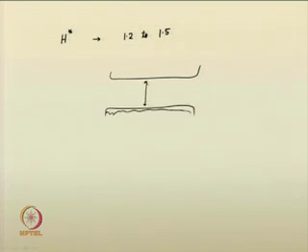This is the culvert depth, this is the headwater depth. So, headwater depth should be above H star, that is the criteria, right. From various experimental investigations they found that H star is approximately 1.2 to 1.5 times the depth of the culvert.